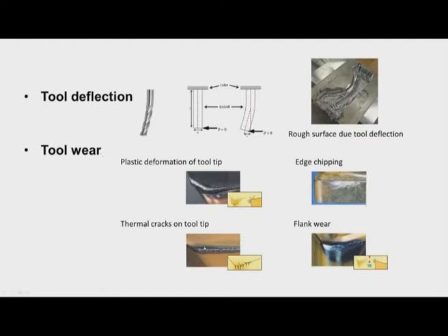There are various kinds of tool wear: the flank wear, or the chipping of the edge of the cutting tool, then the plastic deformation of the tool tip because of the high temperatures developed, and then the thermal cracks developed in the tool. All these factors will affect the dimensional variations and geometry variations of the workpiece.